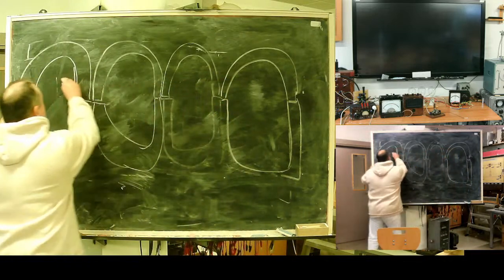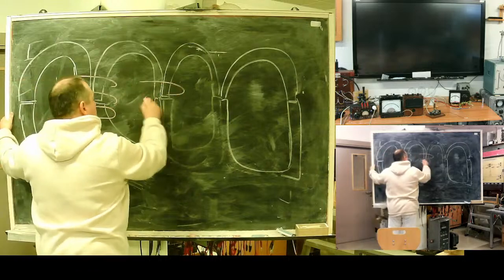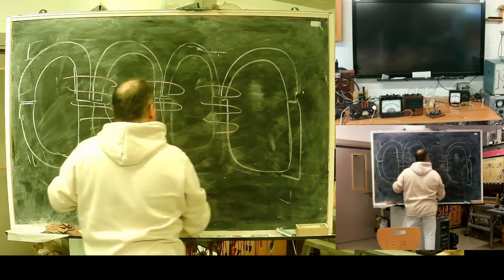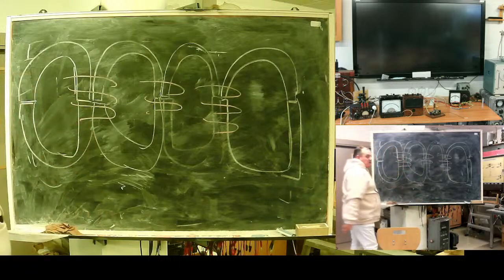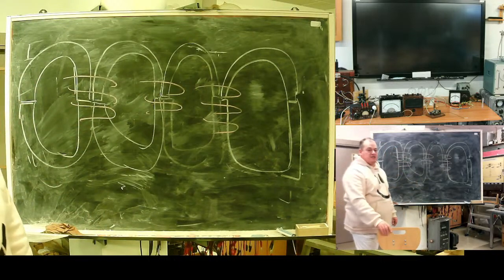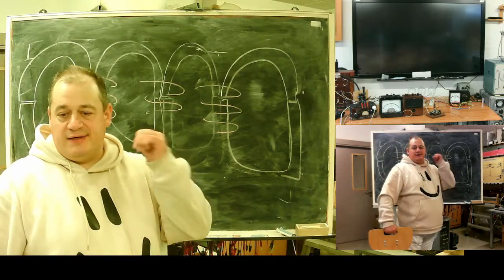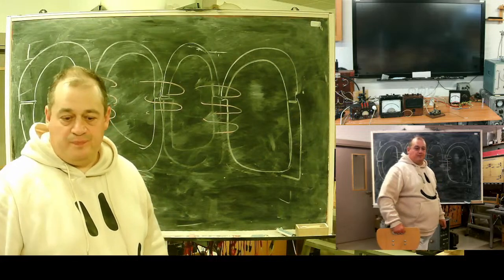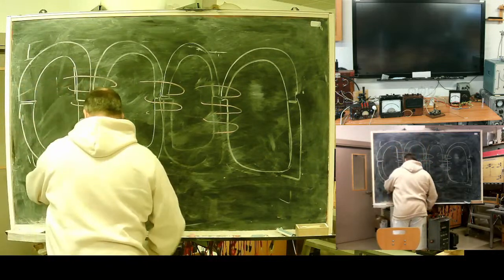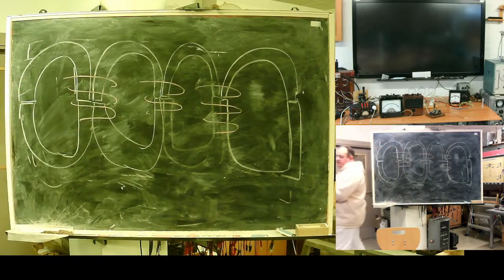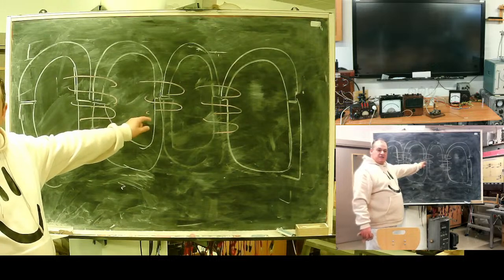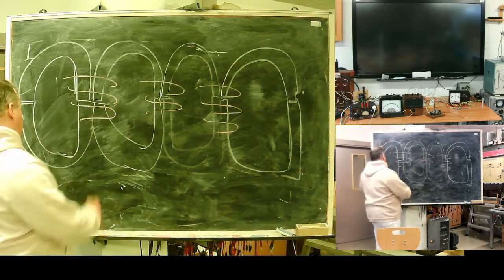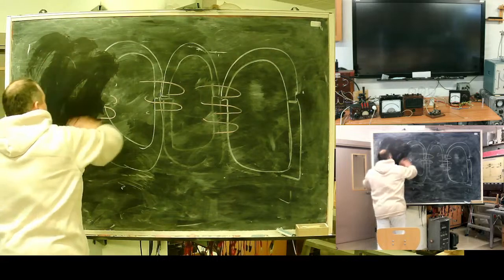And here, rooms for windings. Also a closed magnetic system. Such transformers are strange, but they are very often used in elevators. Somewhere in the regulation it says that an elevator is a kind of high risk machinery, and for high risk machinery, transformers of such design are recommended.